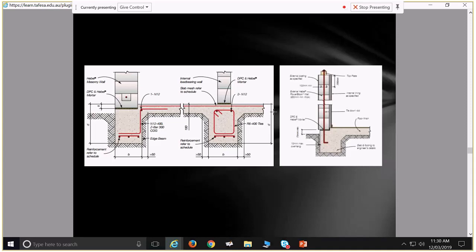And so that concrete and bar ends up tying all of that brickwork to the slab through tension with the concrete bound around it. You can also build a retaining wall in that fashion. You have a foot going back, Besser blocks straight up, and then the weight of your soil goes against that foot to stop the rotation of the wall. But whenever you set your bars in, you don't just poke them into the concrete, because that way you won't get much strength for pulling out. You put what's called a cog on the end, so you bend a section at the end to bind into the concrete.